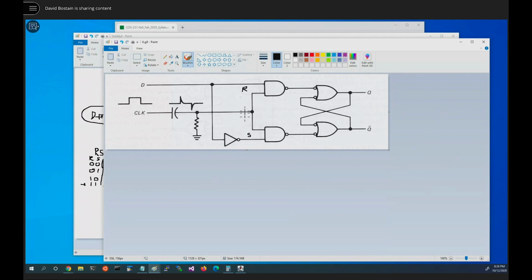This is set and reset even though D is still this signal here. This is not D down here. But as far as what's passing through to the next gate, this might be R prime and S prime, because they only appear during the high part of the clock. That one little point in time way up there. Then the signal passes, and of course that gets latched in, because that's what this thing does if the two are different, depending on whether it's set or reset.